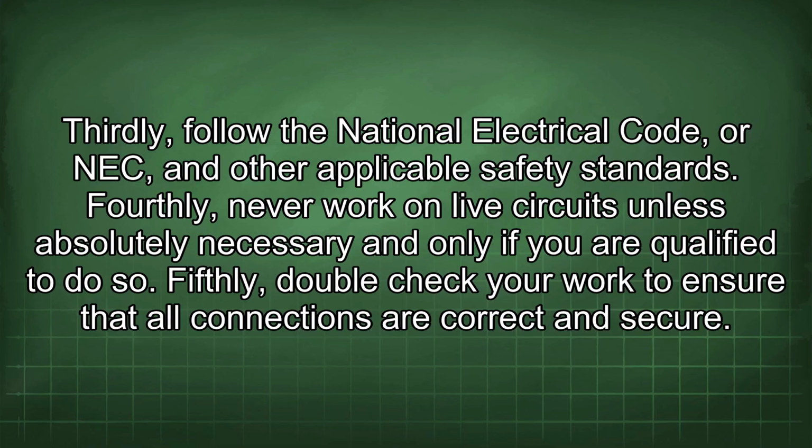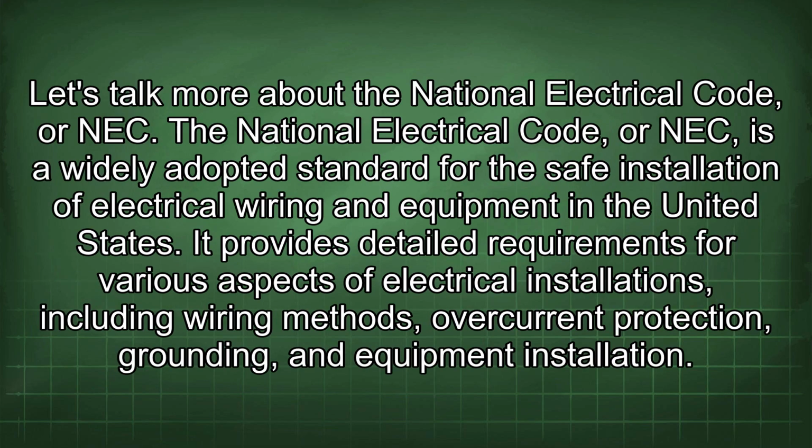Fourthly, never work on live circuits unless absolutely necessary and only if you are qualified to do so. Fifthly, double-check your work to ensure that all connections are correct and secure. Let's talk more about the National Electrical Code, or NEC.